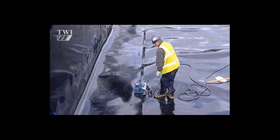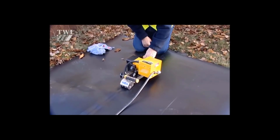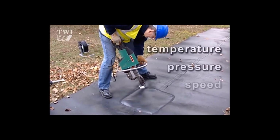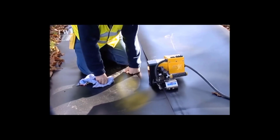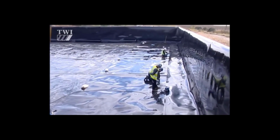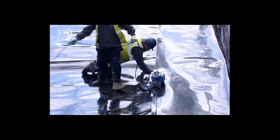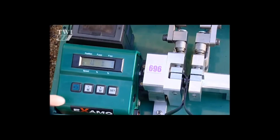Lining technicians need to understand the increasingly sophisticated equipment in use and possess the knowledge to optimize equipment parameters like temperature, pressure, and speed for the task in hand. Coping with different thicknesses of material, alternative equipment, and ever-changing ambient conditions of site work all need to be accommodated safely and competently. A lining technician's knowledge must include the interpretation of weld quality by visual inspection as well as destructive testing methods, using these things: site tensometers.